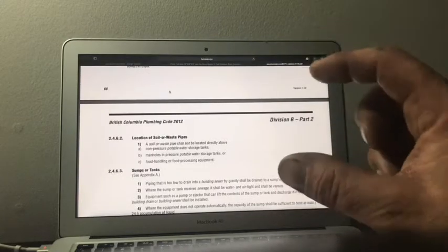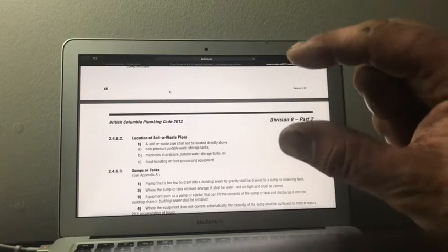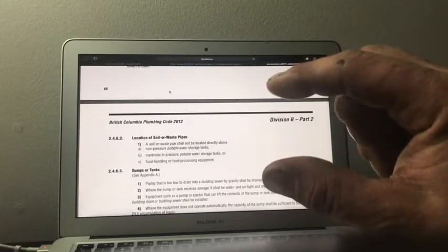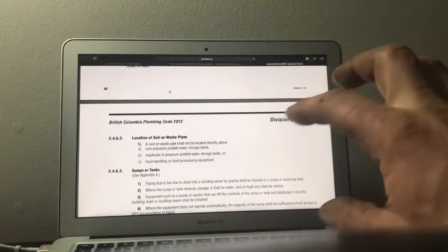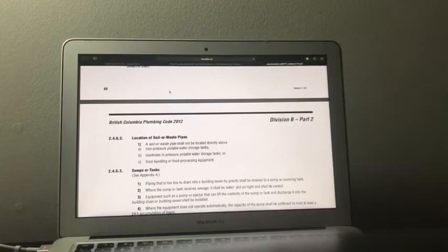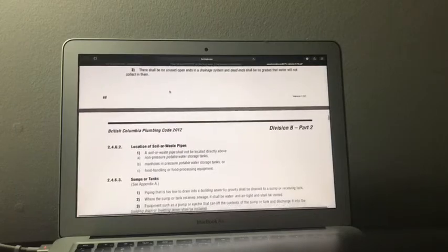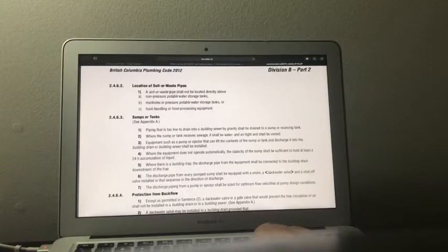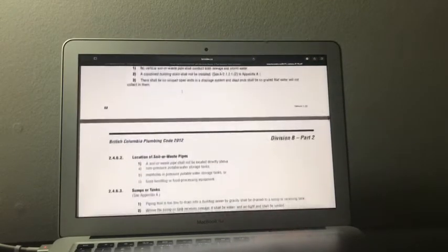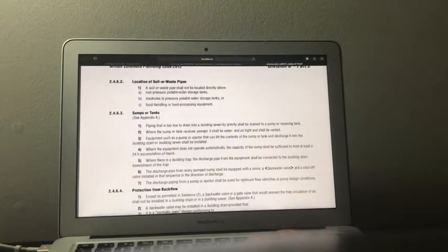So 1.5-inch pipe for ABS, cut her down to an inch and a half, stick a cap on there so you have 3/4 of an inch of piping showing, so you can literally glue another coupling on there and go. So that's how much pipe they want to see showing on those dead ends. So dead end, obviously, just to clear it up for young guys. Abandoning a pipe would be one situation, and I'm sure you can imagine some others.